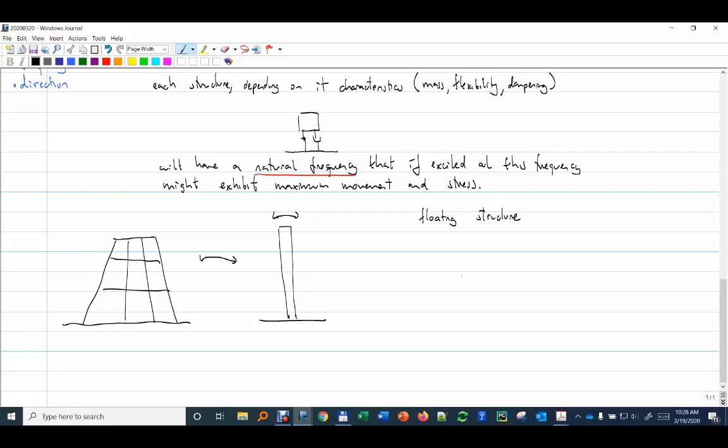a floating structure is a bit more complex. So if we say in the most general case, it is like a ship, or an FPSO. We're going to have essentially a very important movement. We have to be careful. I told you it affects risers, it affects if we have dry Christmas trees. We have heave, moving up and down. Then we have moving front and back. This is called surge.